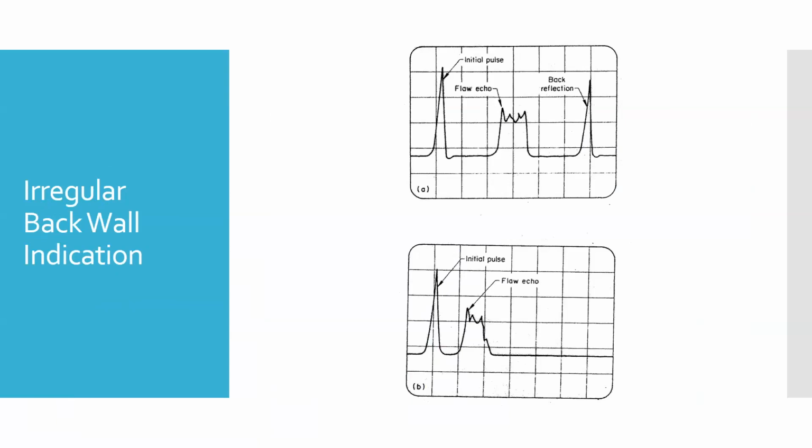The other thing that's happening is the total energy is often going to be smaller, because not only is sound bouncing up, but a sound wave hitting right here probably isn't going to go straight up. It's going to kick off at some kind of an angle, right? So that sound's not going to return to our transmitter, or our transducer. And so it's often a lower energy. You'll see this will be a much shorter pulse than you'll get if you have like a nice smooth crack or something like that.